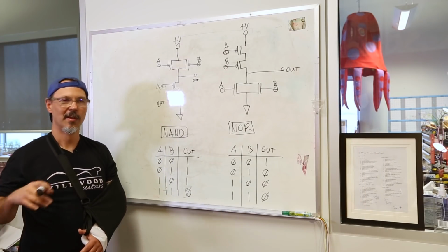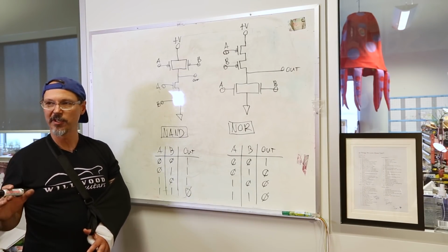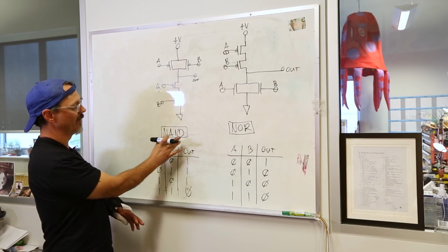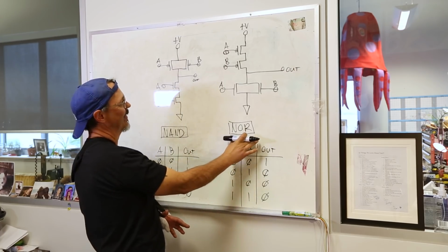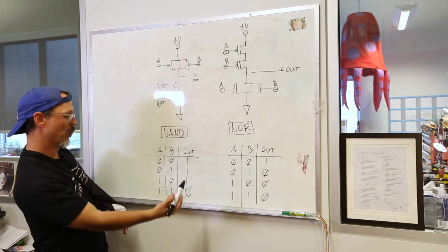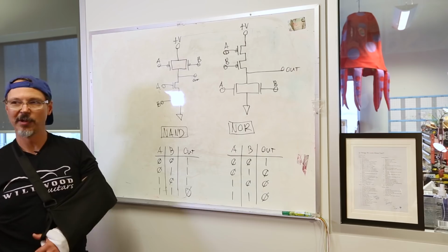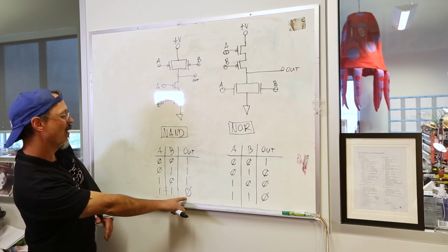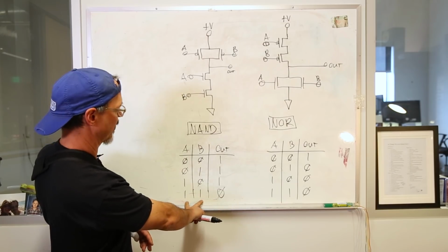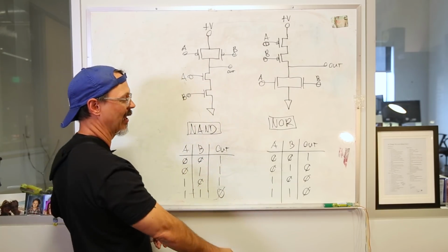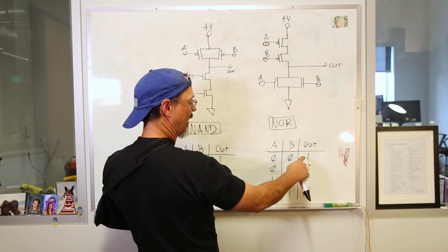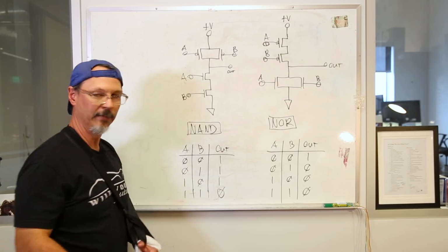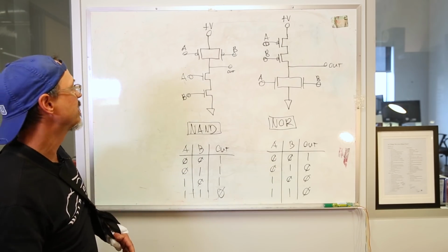All right, now we're going to look at the other circuit. Okay, MOSFETs. When you go to MOSFETs, some really interesting things happen. Now, we've got 2 circuits drawn here. One is a NAND gate, one is a NOR gate. And for reference, I have put the truth tables down. Now, a NAND gate, basically, the output doesn't go low until you've got both inputs high, and that'll bear out in the analysis here. For a NOR gate, the output is high only when both inputs are low, okay? Again, this will bear out in the analysis.